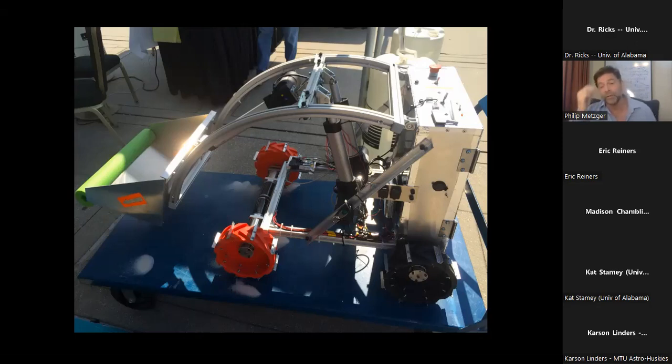Now, here's the deal. You almost can't prevent this. There is a way to prevent it. There are multiple ways to prevent it, but you've got to know about it and think about it to prevent that from happening. If you don't prevent it and you get wheel diagonalization, you now have effectively a two-wheel vehicle, because two of the wheels, let's say the right front and the left rear, no longer have good traction on the soil anymore. And so if your vehicle has enough margin in its torque and its gear ratio, then you can drive forward on the remaining two wheels and get out of that situation.